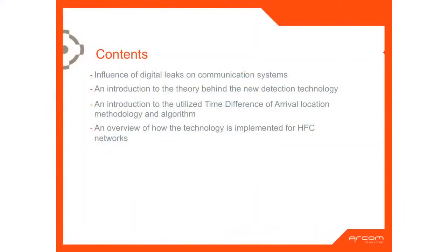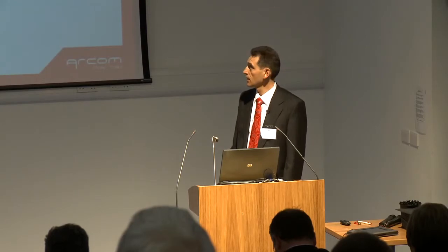I will explain what we found in regards to influence on communication systems by the digital leaks. Then I'll explain what new technology for reading leaking signals from digital networks we can use in real life. Then I'll explain what methods of ranging the leakage sources we are using. This is called time difference of arrival. And I'll show you how this technology can be implemented in an HFC network in a scalable way.